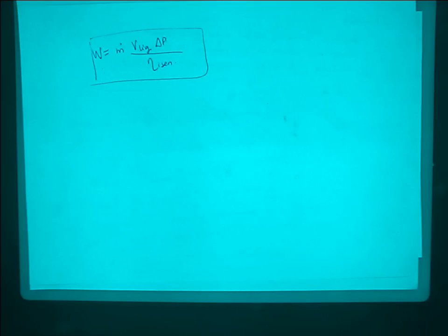So let's say we have this system, where is the isentropic? Here is where we have the isentropic, no? So I could ask you to calculate the isentropic efficiency, if I give you the T at the inlet and at the outlet. So yes, you could calculate the isentropic efficiency if you had the real temperature and the temperature at isentropic conditions.